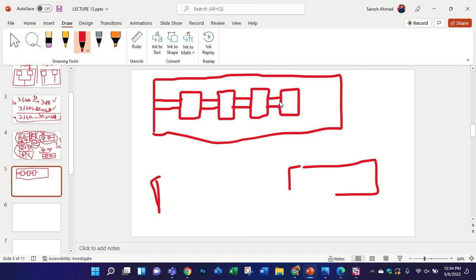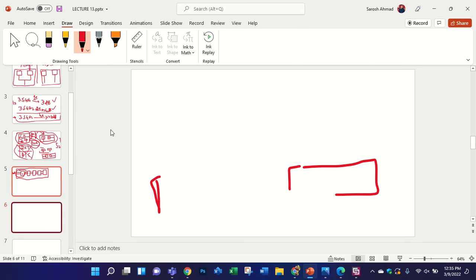There are many techniques that you can apply. Let me share some techniques that I have seen in papers, how they have divided and used the antenna array. This is one technique. They have used a port here and excited the antenna from here. They have a feed line here and just repeat this step, dividing this part into multiple antennas, like this one: patch 1, patch 2, 3, 4 and 5. In this way you can also increase the gain of the antenna or make a directional radiation pattern.